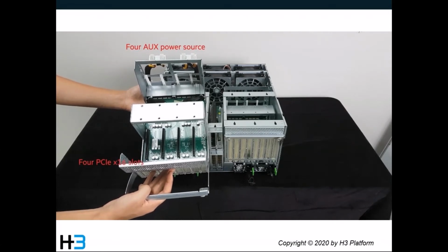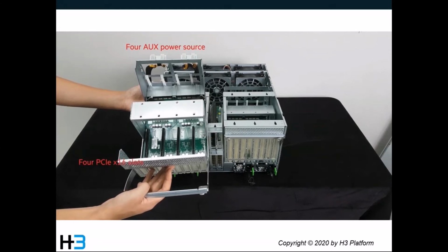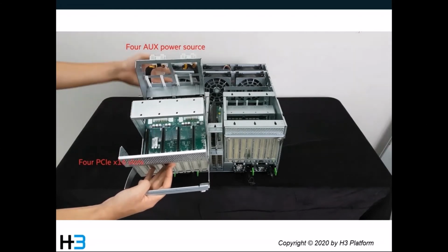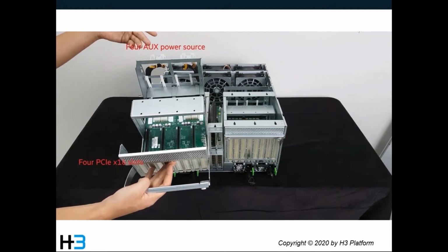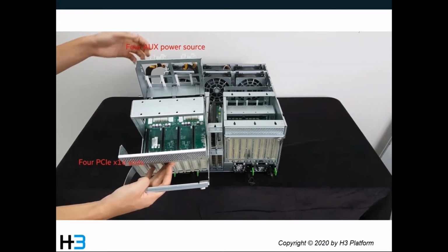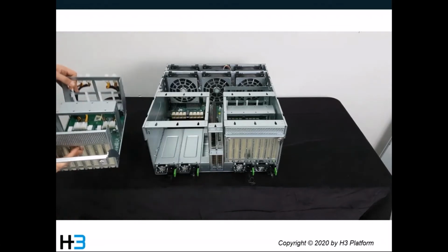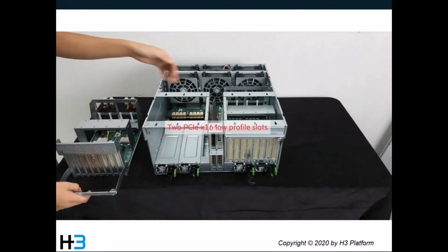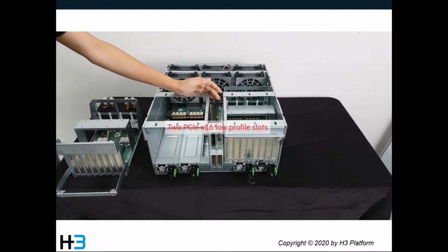A slot will provide 75 watts of power, and the remaining power will be provided by the 8-pin aux power source at the back. Also, there are 2 more low profile x16 slots in the middle, and these are for any other devices you'd like to install.